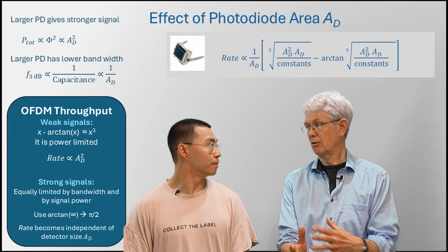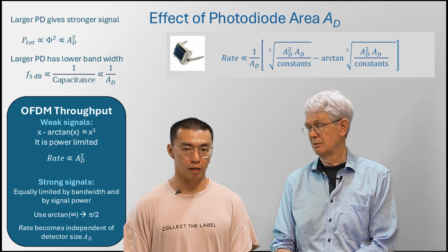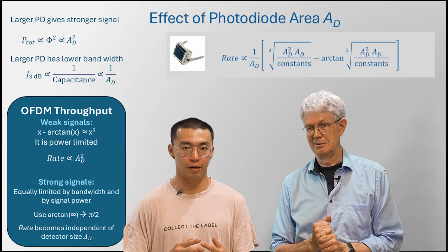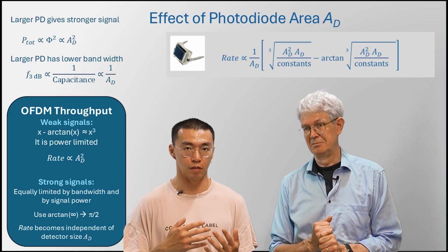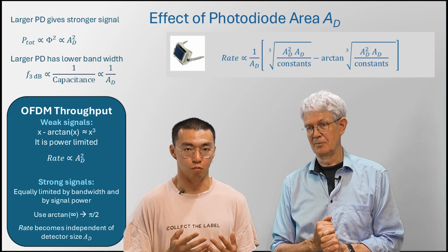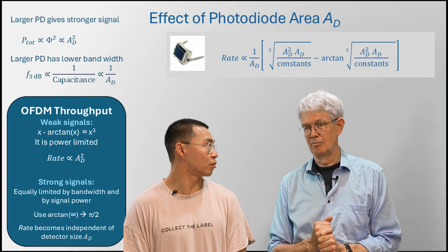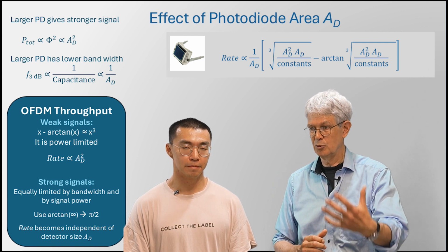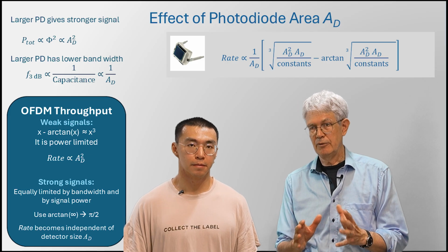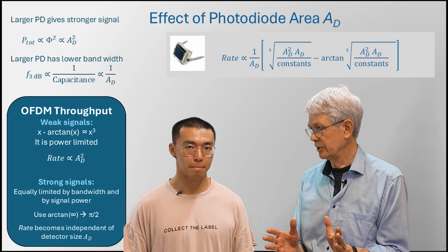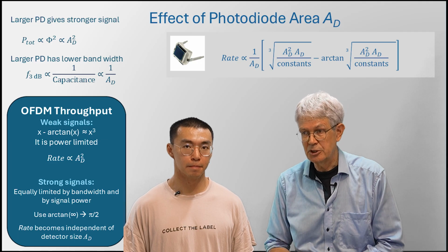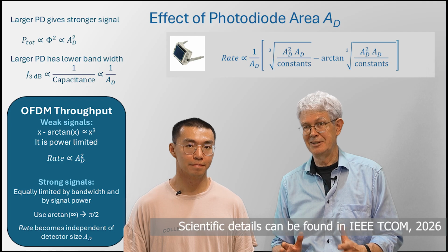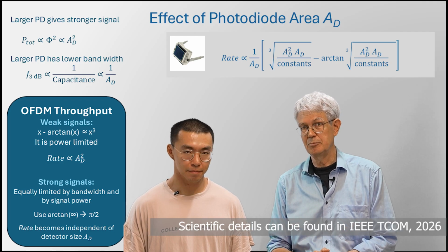So it doesn't matter how large I make my photodiode. Yes, if we model the photodiode as a first order low pass, then for a sufficient signal power budget, the size of the photodetector doesn't matter anymore. So in theory, for relatively small, weak signals, make the photodiode as large as possible. For stronger signals, there are other engineering constraints. But anyhow, having these expressions can be very useful. Some people said there is nothing as practical as good theory, and this may help to design a system.